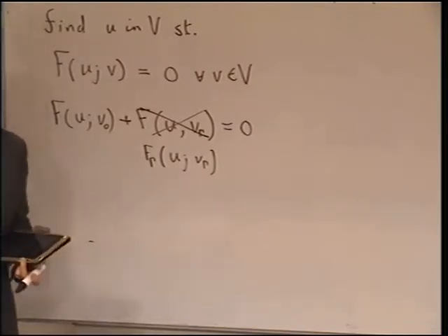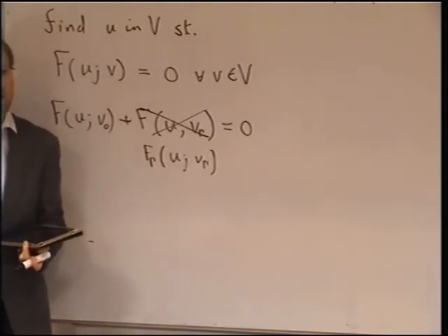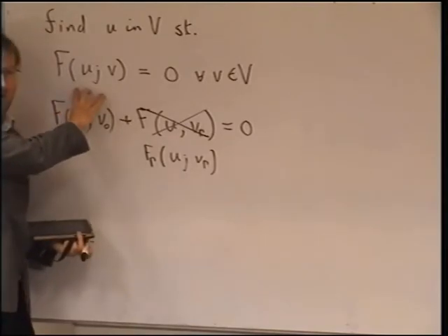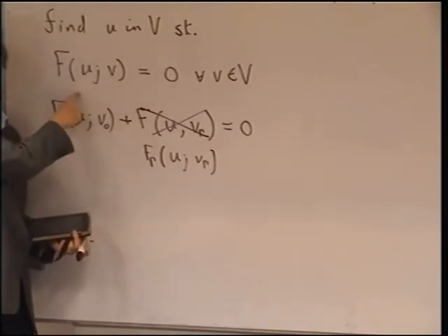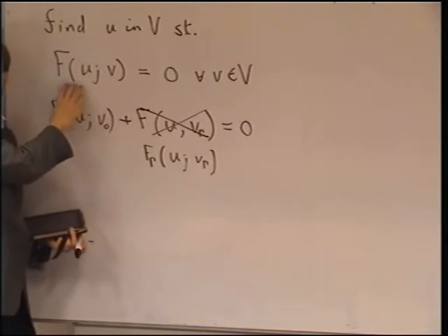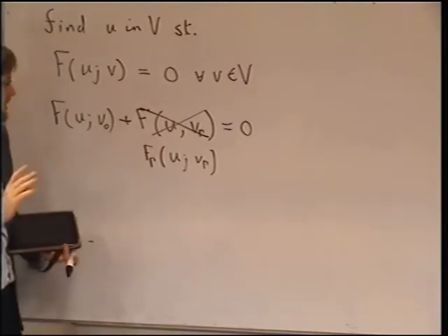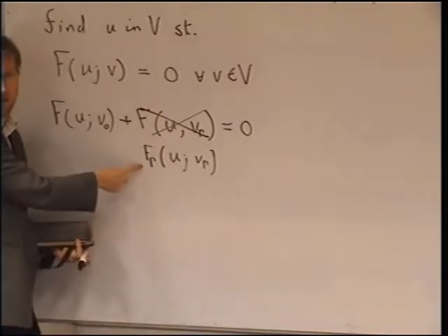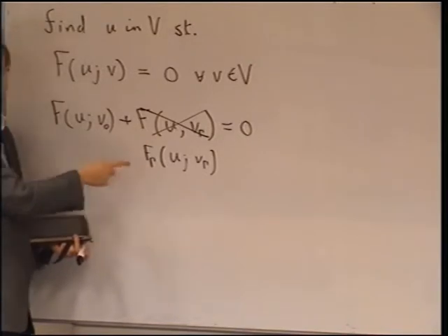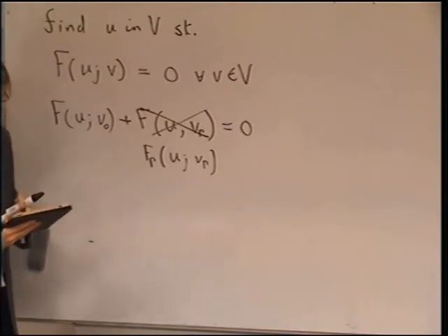Well, it's not quite all I need, because if we remember back to last week's lecture, the way we got to actually solve this problem was we differentiated this guy using a Gateaux derivative so that we could use Newton's method. So having got a beautiful differential form, which in most circumstances that we care about is differentiable, and so this works for us, I really, really don't want to break that by introducing a non-differentiable function here. So I'd really love that to happen.